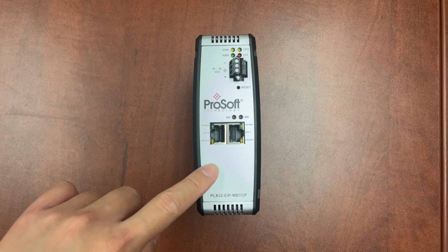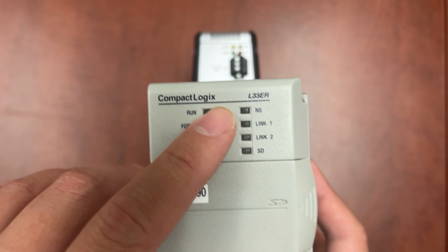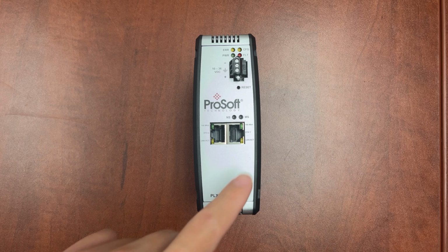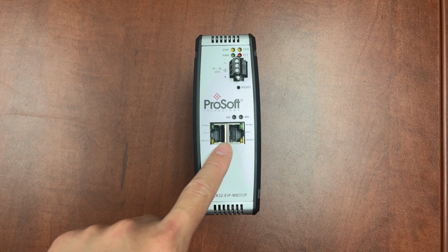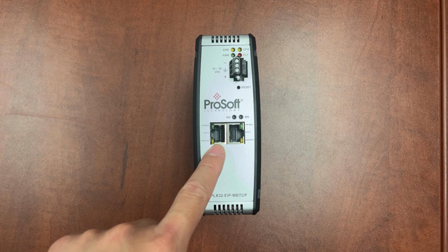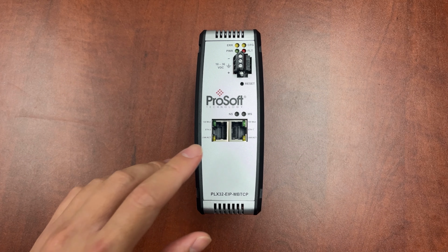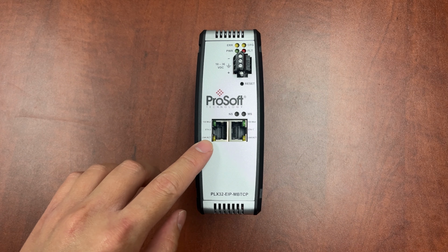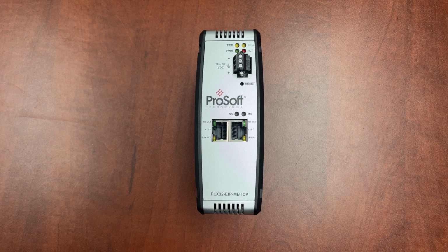The gateway will grab data from an Allen Bradley Compact Logic PLC over Ethernet IP from Ethernet 1 port and convert it to Modbus TCP that resides on Ethernet 2 port. This port will be reserved for customer to avoid any possible IP conflicts when both customer network and the local equipment network are connected to the same gateway.